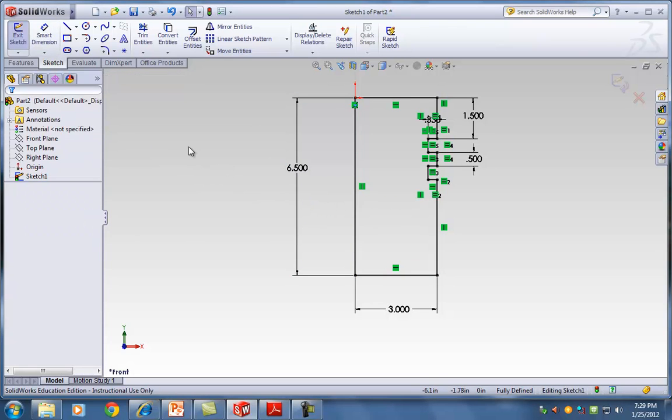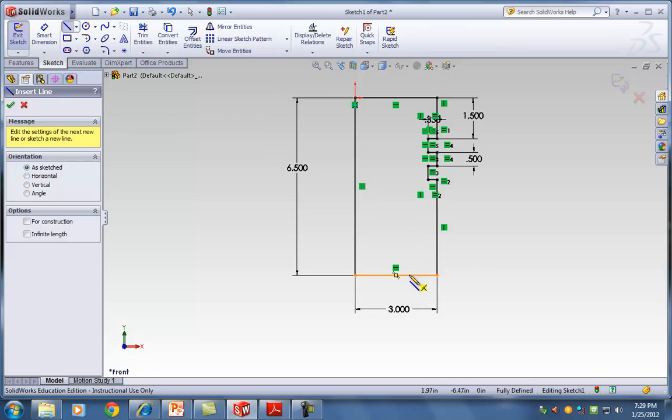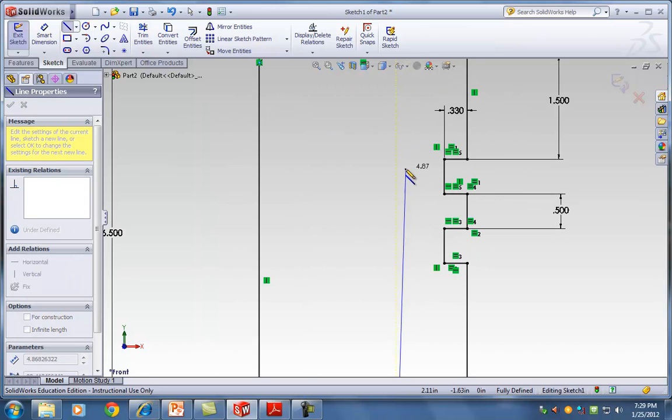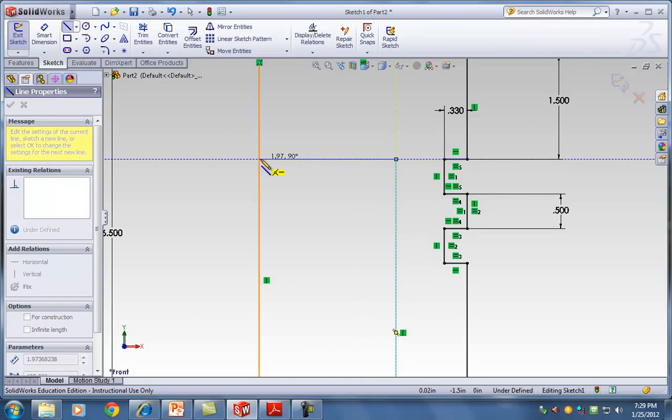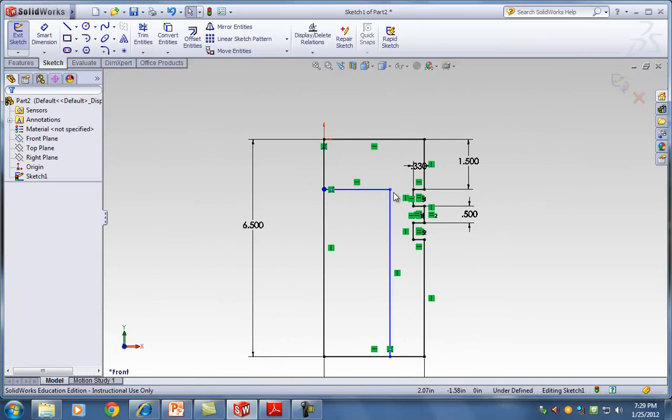So you should have a fully defined sketch. Now what happens if we grab this and we revolve it around this line? It's going to be solid. So how can we fix it? Exactly. So we can add an additional line here that symbolizes exactly how high we want it from here to here. And everything else is pretty much trim.